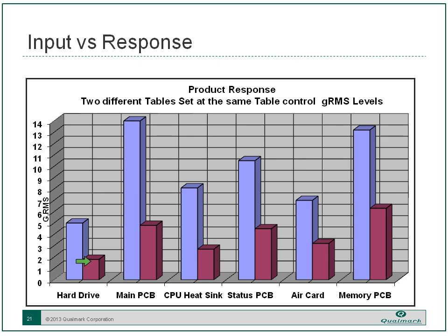In the end, when you finish HALT and you have your operating and destruct limits, those limits need to be in terms of product measurements, not chamber set points.